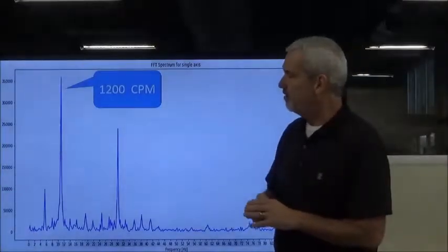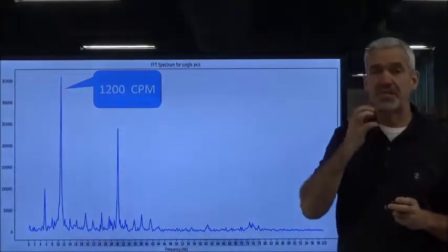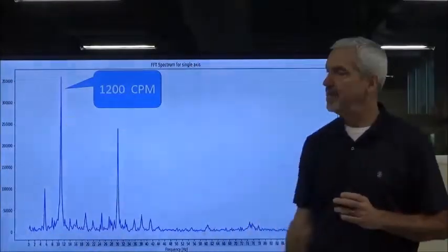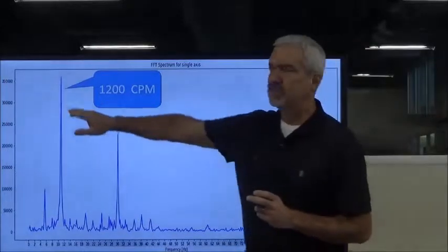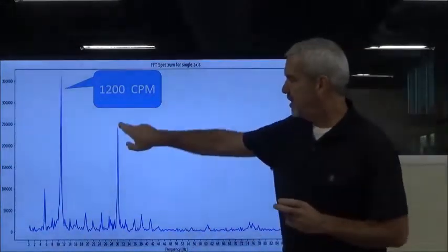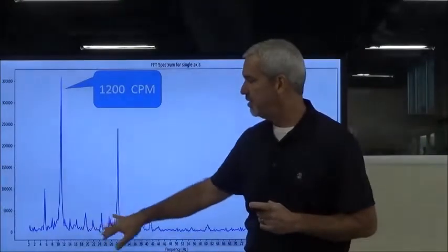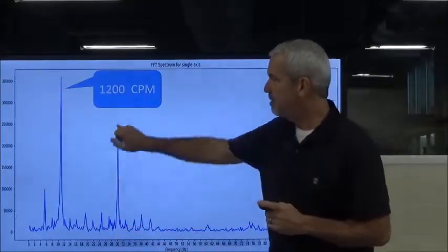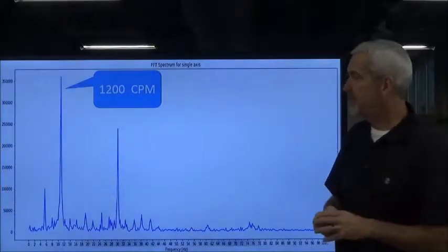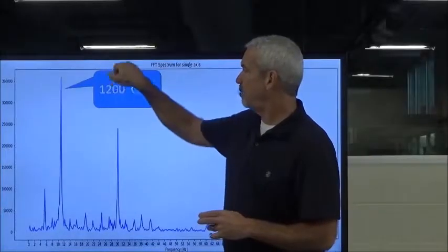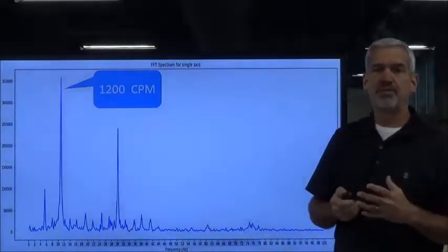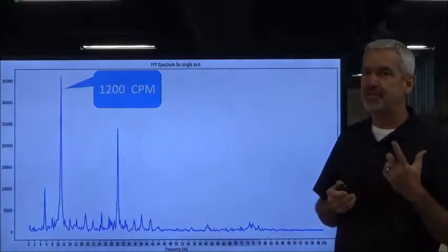right there. Most vibration does come from imbalance. So this is your lower cycles per minute, so it's going to be on your left-hand side. And most of the vibration that we run across is a result of imbalance. However, you see these peaks right here that are much higher, further down in the spectrum. This could possibly be a gear mesh frequency or something too. But my point is that the predominant frequency could very well be higher in amplitude than this one.